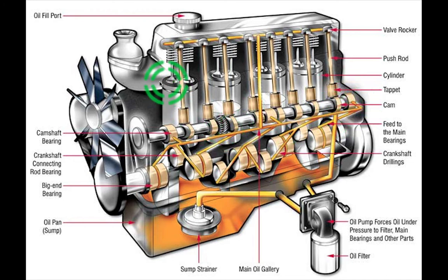And then finally, for your piston, there is oil provided between your oil ring. In that groove, you will see some holes for the oil to come out from there, so that there is never metal to metal. As you can see, this is your piston and this is your cylinder. The piston is this thing inside, like they've made it like a transparent glass kind of thing, and inside that your piston is sitting. So you have your oil here.